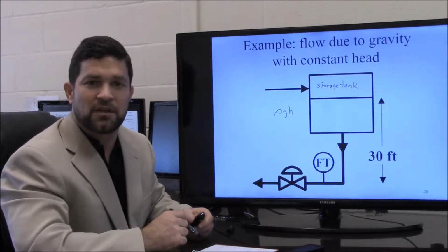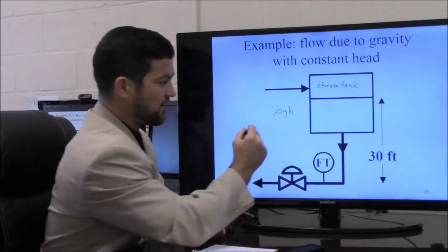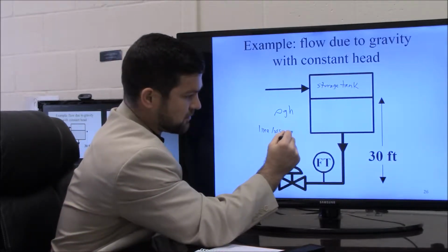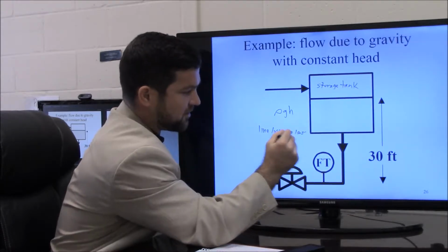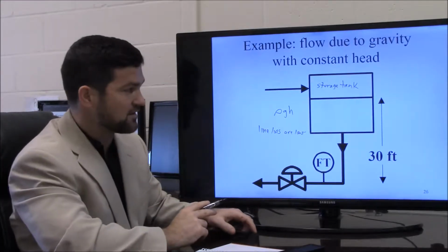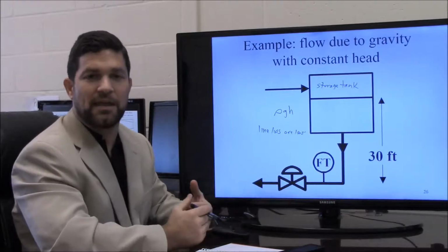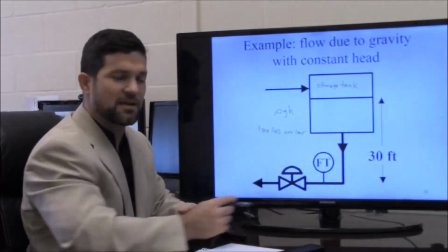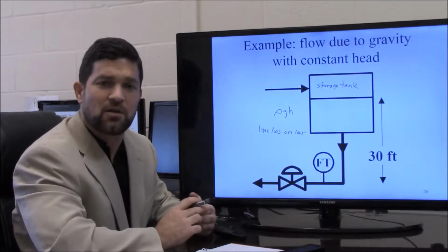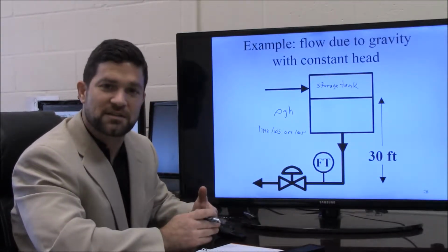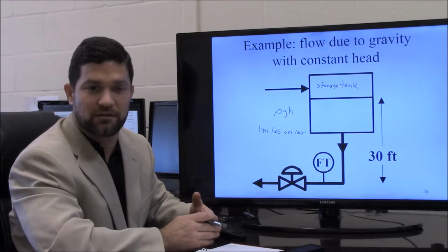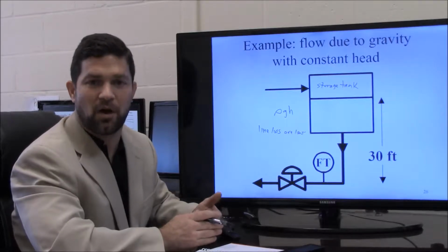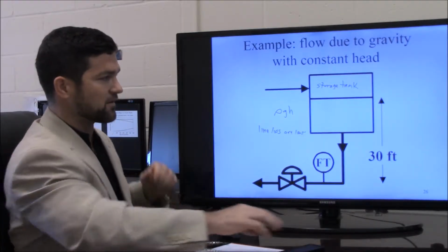across this valve. The other important assumption to consider here is that the line losses are low, or small, for the system. Right, so if the line losses are small, and the pressure generated based on the height of the fluid is constant, we would expect to have a relatively constant pressure drop across the valve. And if this is the case, like we mentioned, a linear valve is probably best. So let's see how that goes.